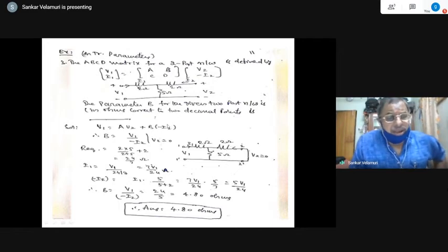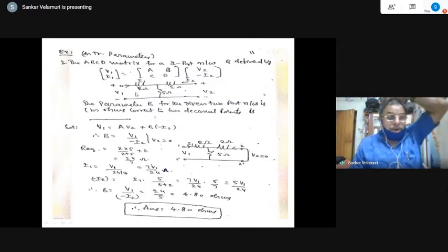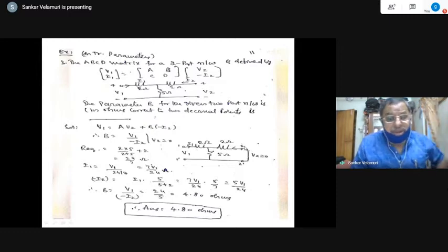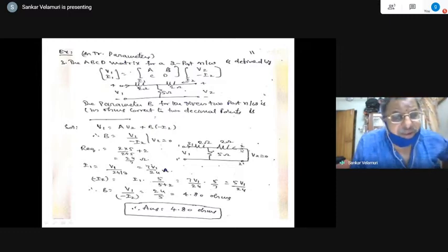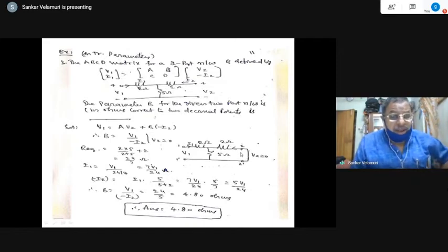Now, without understanding that or without having that clue, you follow the systematic method. What I mean to say is, for practice sessions, you have to solve methodologically and systematically. But if you have a thorough idea in your mind and have already tried similar types of problems, identifying this type of problem, then you can go straight to the answer, stating that yes, the transfer impedance is the same as B. So converting this T into a pi network, the equivalent star-to-delta conversion of the element that would have been connected between the two ports is the answer. The value of that is the answer. That way you can do it, not as a guess, if you are thorough with that.